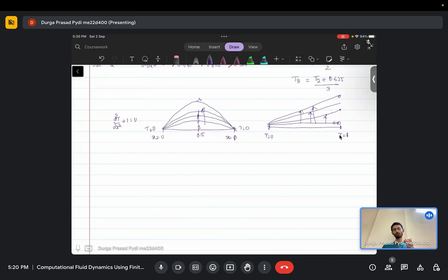This is something we were discussing for convergence criteria. If you have a Dirichlet condition, your convergence is kind of assured because this is how the information will propagate. But when you have Neumann type conditions, you don't have this information. You just say the flux is 0, so no information comes in. Unless you specify the temperature or some reference, only then will the information propagate inside and your iterations converge.